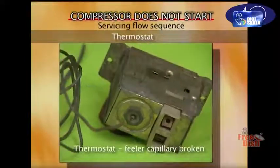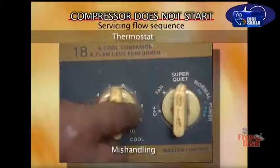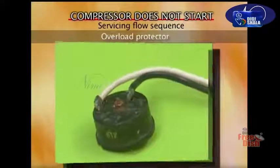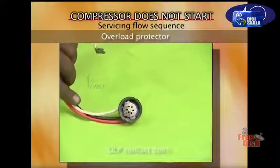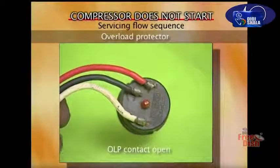The thermostat feeler capillary could have been broken, or there could be just some mishandling. Check the overload protector. The overload protector contact could have opened.